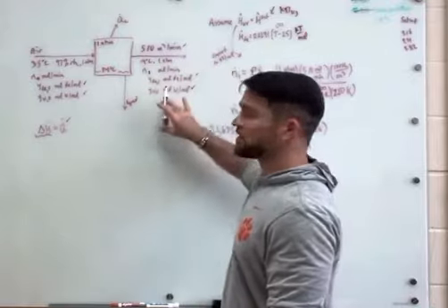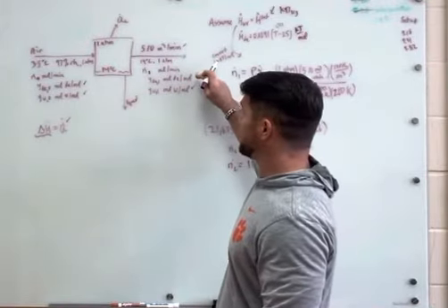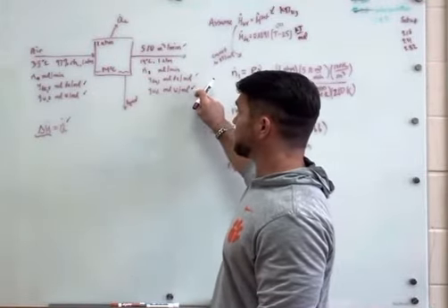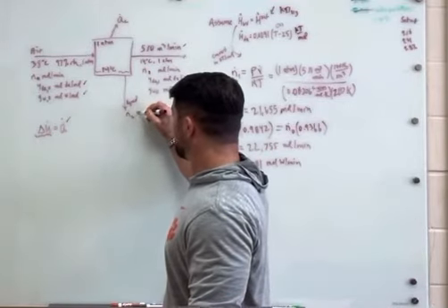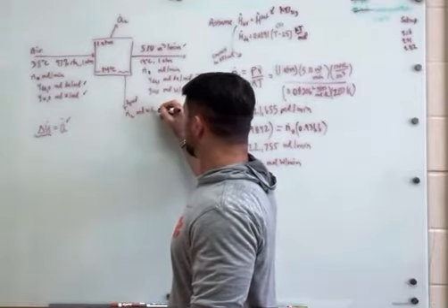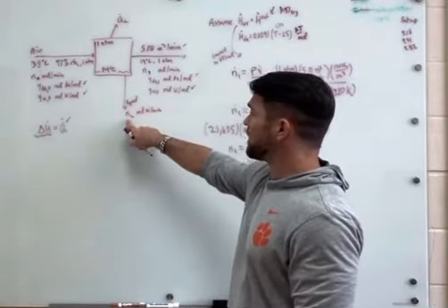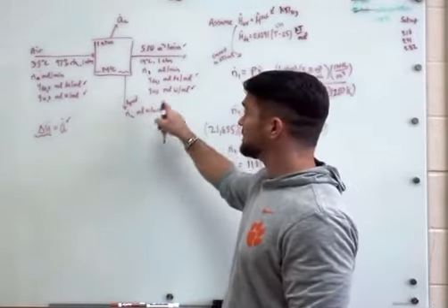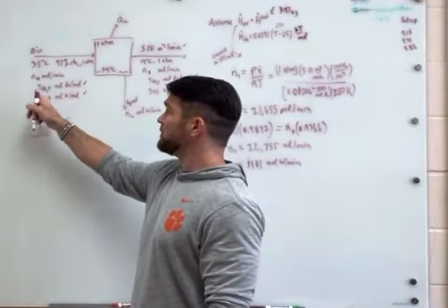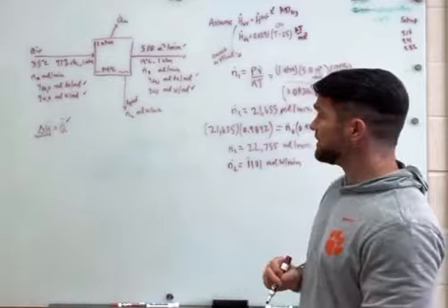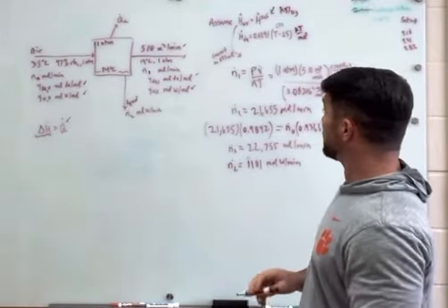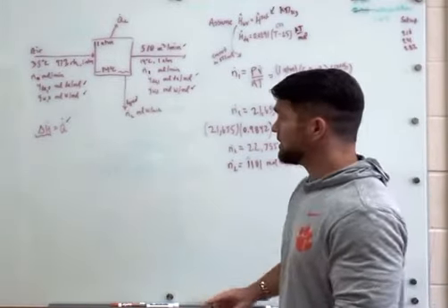Looking at the species coming out, we have dry air in the vapor, water in the vapor, and then water in the liquid, with the L moles water per minute. We have to consider all of those enthalpies coming out. Then we have dry air coming in and water coming in. So I'm going to need enthalpies for each one of those things.